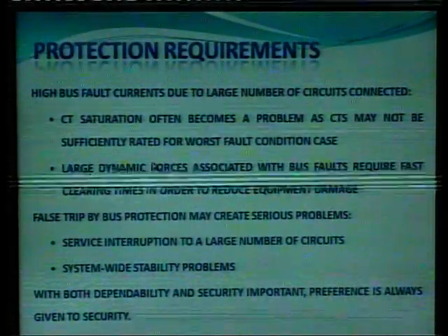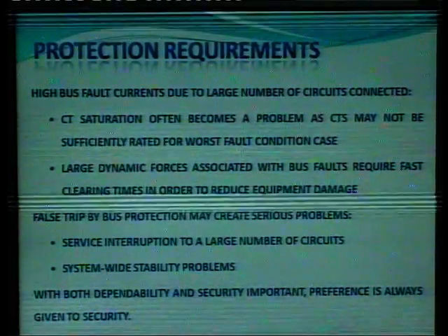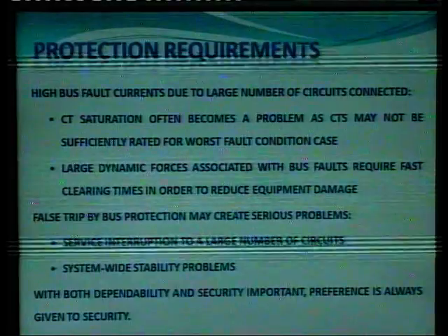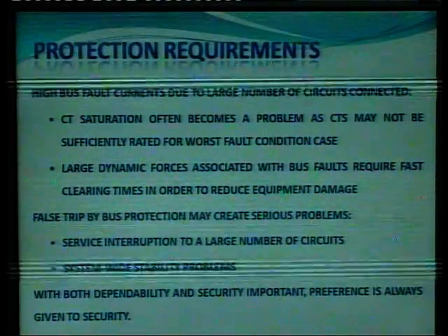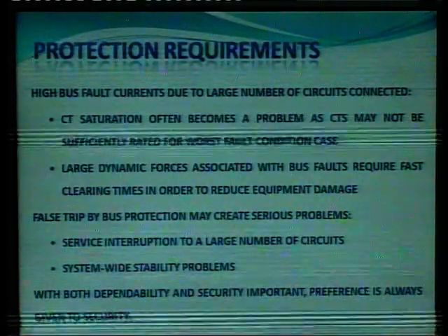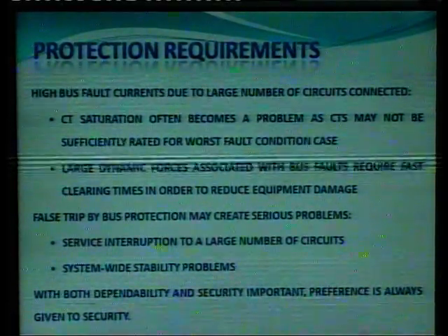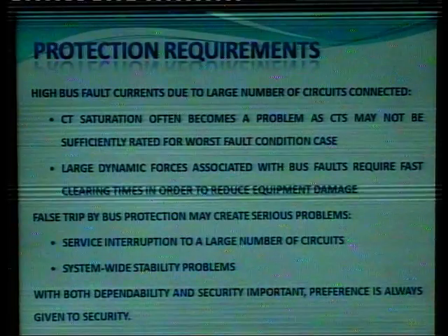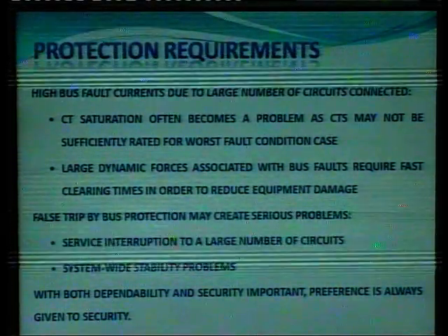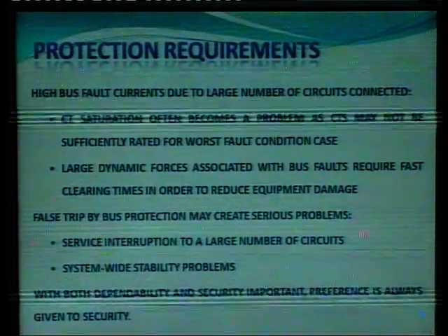Now, why is there a requirement for the protection of the bus bar? Now, first is high bus fault currents due to the large number of circuits connected, which causes CT saturation; often it becomes a problem as CTs may not be sufficiently rated for the worst fault condition case.